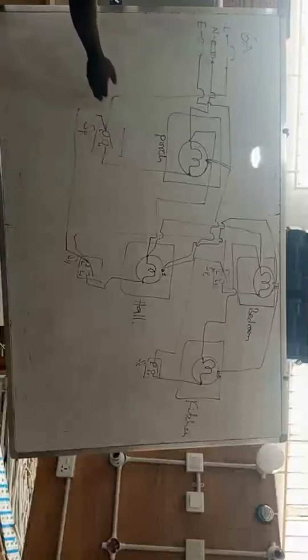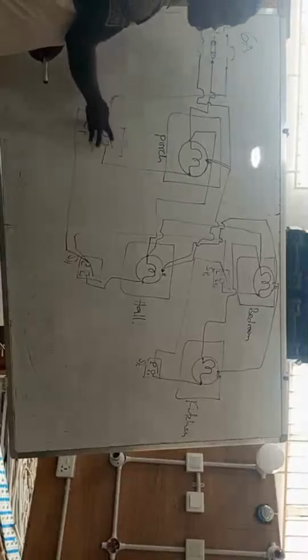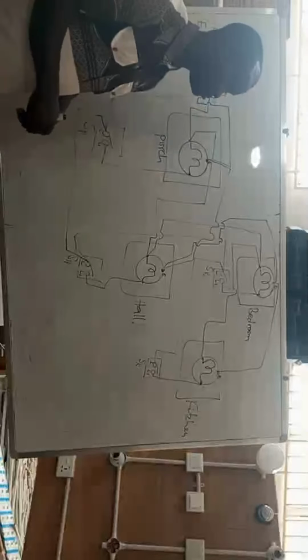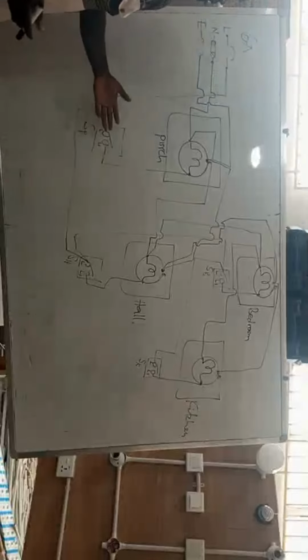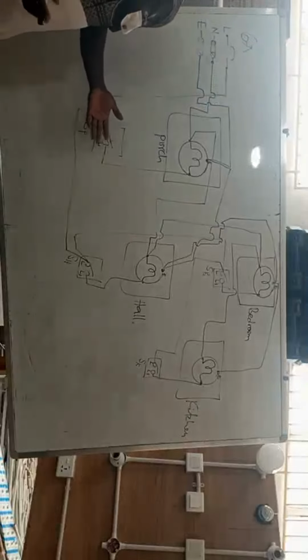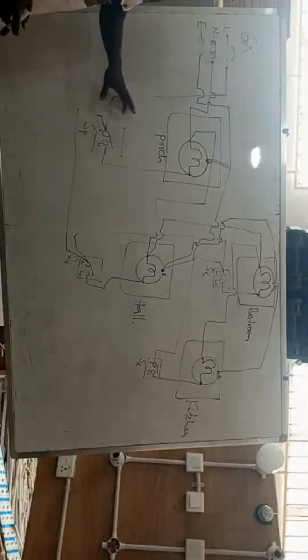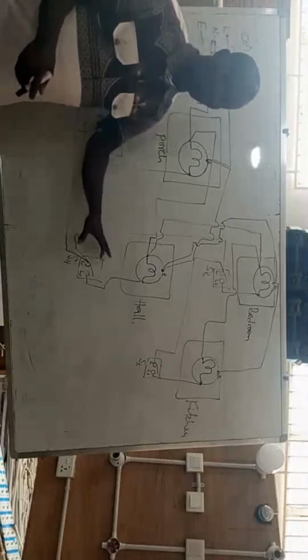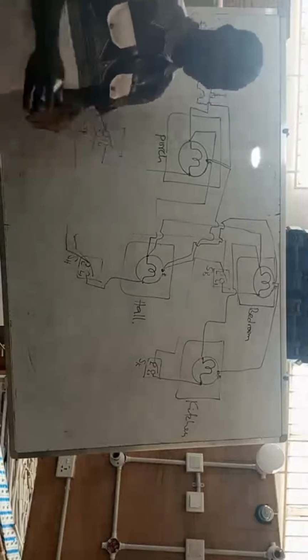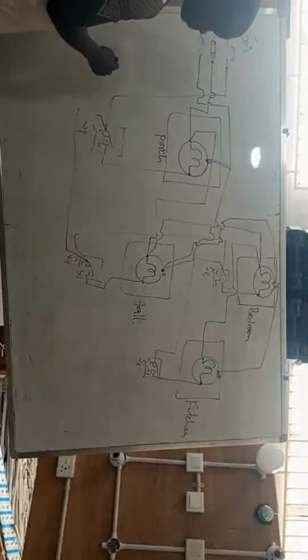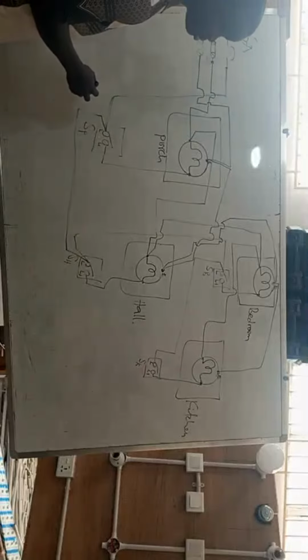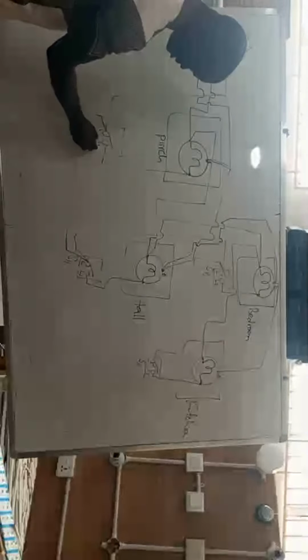Now, if the boxes you use here, which is typically the case, most of the time when we are doing conduit wiring, the boxes we use sometimes are metal. So if those boxes are metal boxes, then we still have to earth them or connect earth to them. So in that case, let's say we have an earthing terminal here.